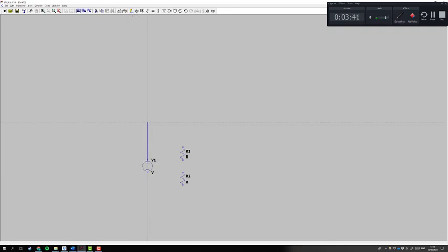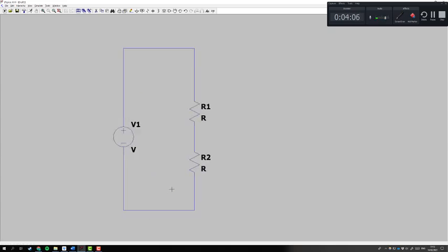The next thing we're going to do is to draw a wire, because you obviously need to connect up your circuit. So click, click, click, and then click. Oops. Right, try it again. Click from there to there, and from there to here, and in you go. Escape to finish. Now we've got a basic circuit. This is called a potential divider circuit.